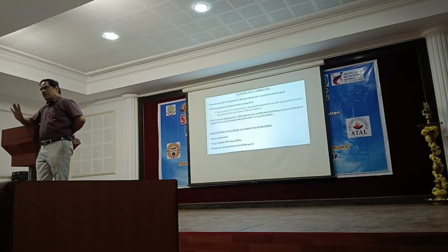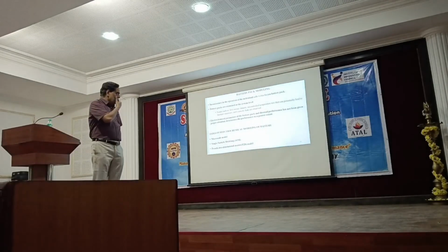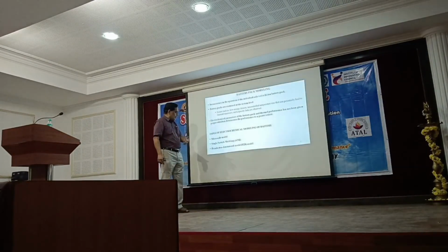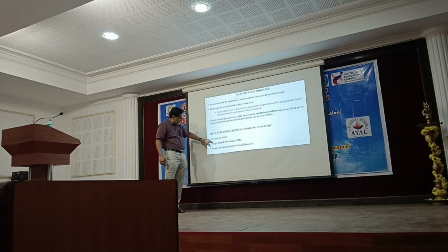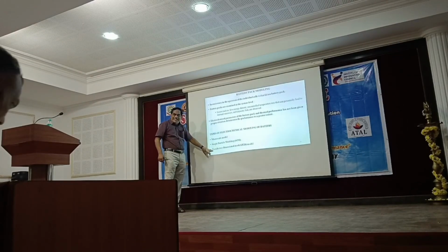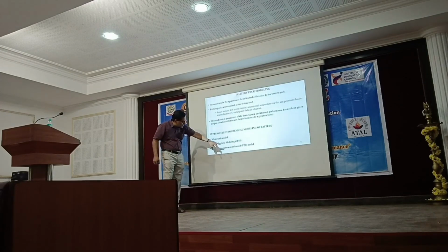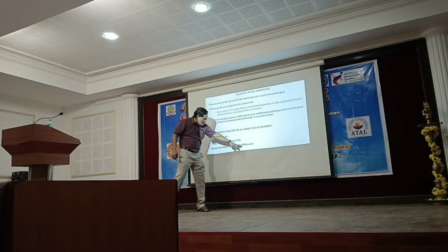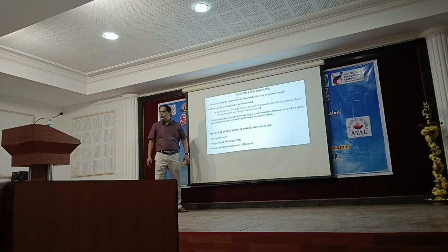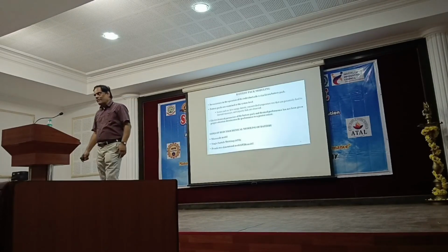Okay, having discussed capacity, we need to know how to model a cell or a battery pack by going to electrochemical modeling. The variety of modeling we have: microscale model, single particle model. What I am going to discuss is the less computationally intensive pseudo two-dimensional model, the P2D model. This is the model we use to estimate SOC of the battery pack.